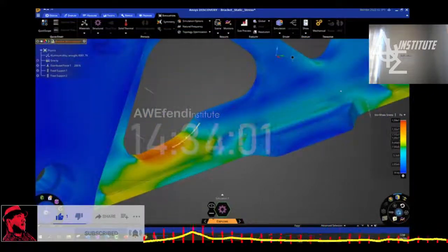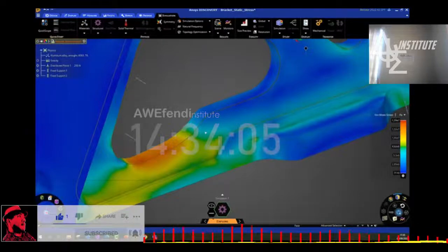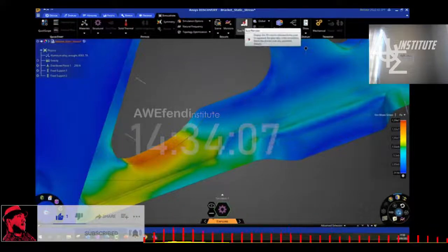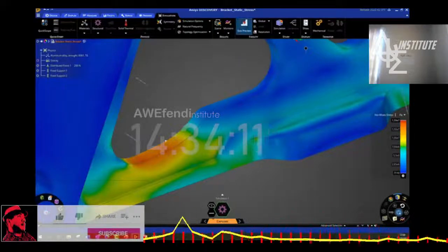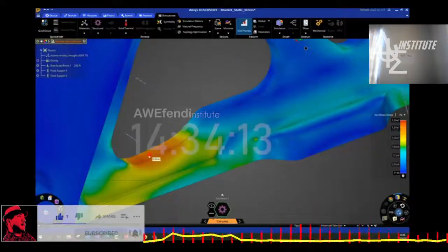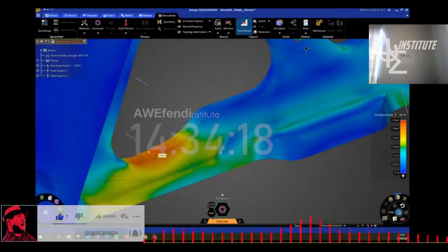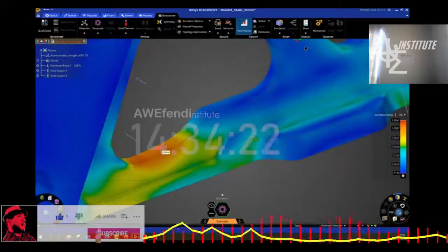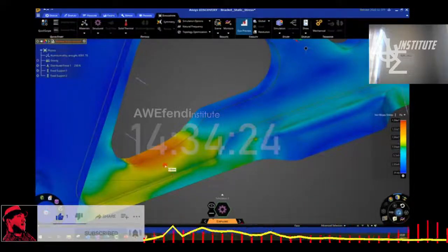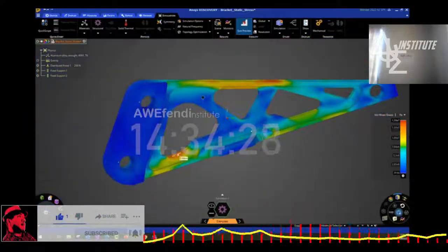And I'm curious, what is the problem over here? Does the mesh have an influence? Because with the explore mode, you can't really visualize the mesh. What you can do is preview the size of the average mesh by clicking on this button. And when you hover over it, you can see, for example, it's using a mesh of 0.85 millimeters. But I would like to see the mesh itself, how the domain is divided, and if I need a finer mesh in that area.